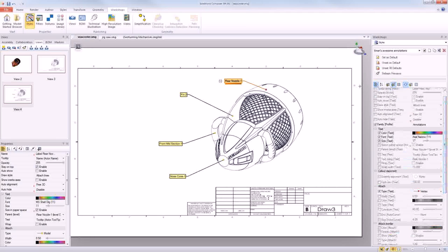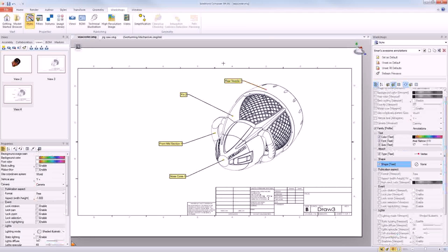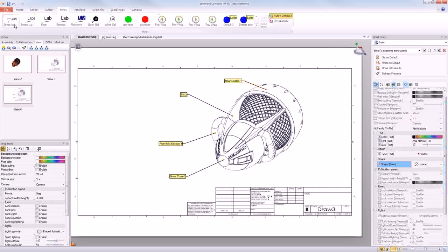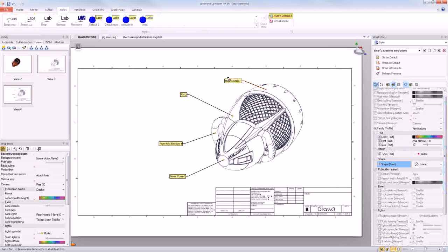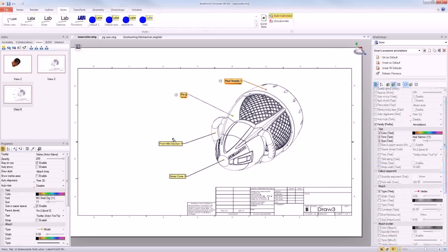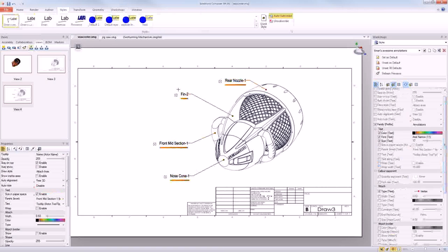Okay? Once I've done this, I can look at my Styles tab, and look what I have here. It's called E-Man's Awesome Annotation Style, ready and available for me. So if I go over and I click on a couple of these existing annotations over here, I can paint them with my annotation style, and they'll all update with the properties that I defined within my style.